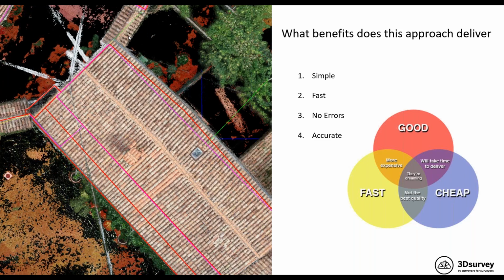We saw how fast we were able to map almost all of that area. So it took us less than 30 minutes, which makes it considerably faster than using a total station. And it is less prone to errors. So we are less likely to make a gross error when connecting some building outlines. Also, it will be a lot easier to access the back sides of the buildings that are sometimes very hard to reach with a total station.